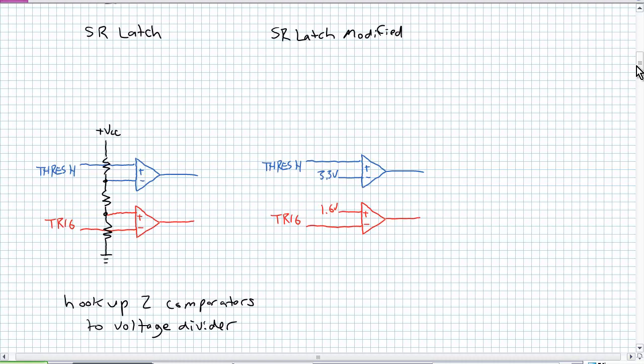Okay, remember back to our pinout diagram for the 555. The upper comparator's minus input is on that 2/3 of VCC input. Where's its output going? We'll figure out where it's going later. Okay, the red, i.e. the lower comparator, its plus input is on that 1/3 VCC, and I've got a trigger going to the outside of that chip. Where's its output going? We'll figure that out in a second.